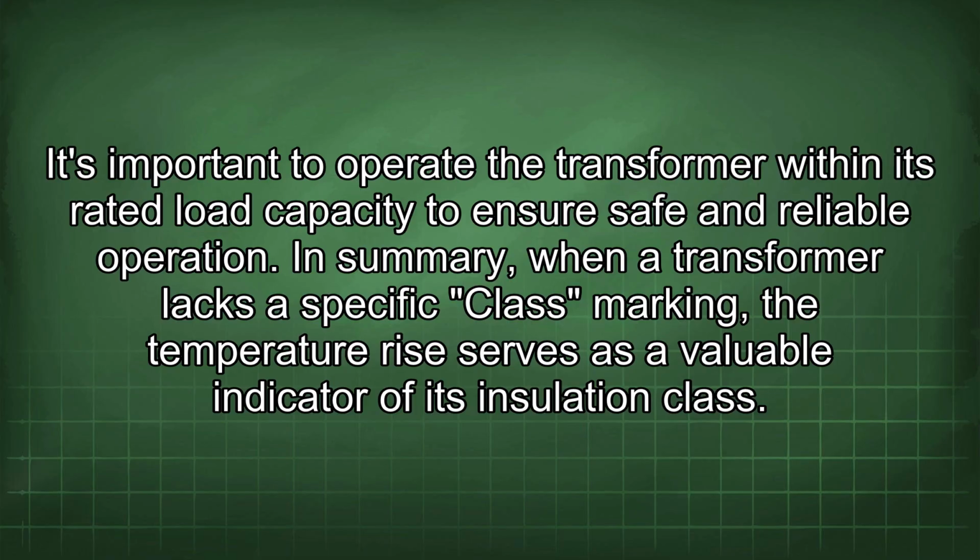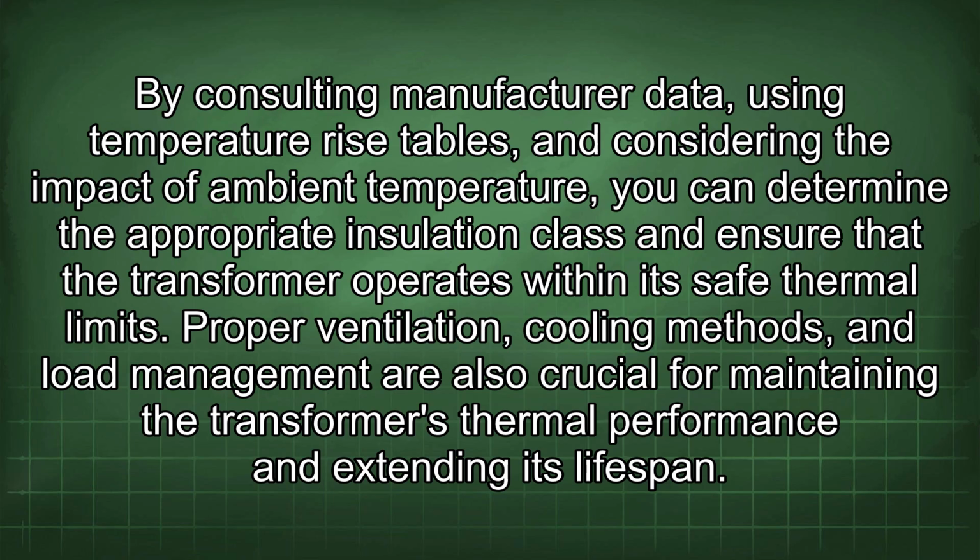In summary, when a transformer lacks a specific class marking, the temperature rise serves as a valuable indicator of its insulation class. By consulting manufacturer data, using temperature rise tables, and considering the impact of ambient temperature, you can determine the appropriate insulation class and ensure that the transformer operates within its safe thermal limits. Proper ventilation, cooling methods, and load management are also crucial for maintaining the transformer's thermal performance and extending its lifespan.